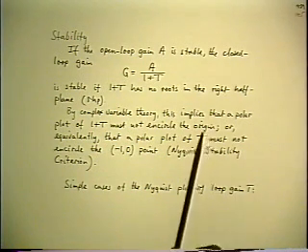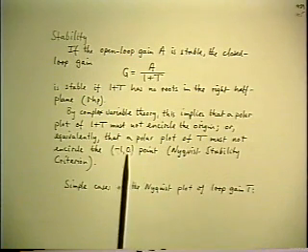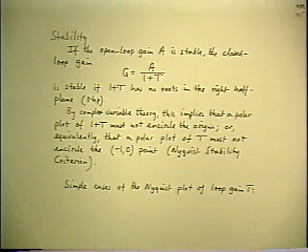And it's in that form that you normally see the Nyquist stability criterion. The polar plot of T must not encircle the -1 point. So that's in all the books. What you don't find in so many books is what polar plots really look like for some useful cases. So let's talk about that.